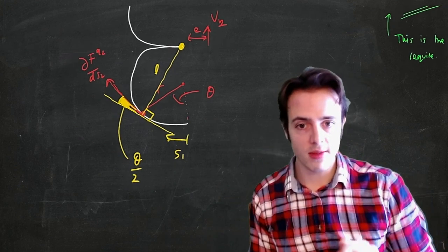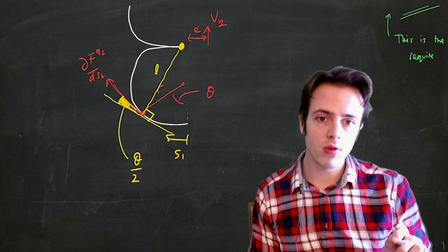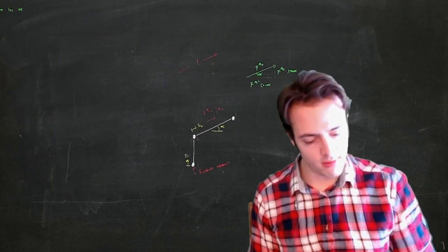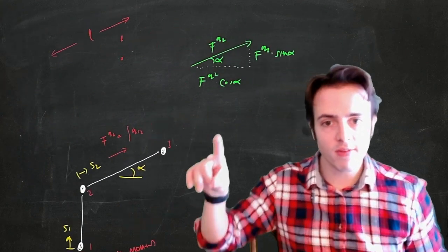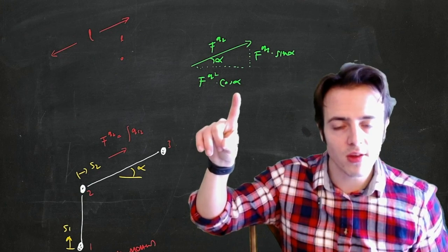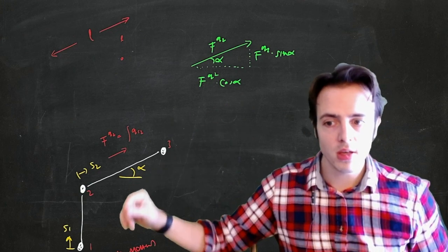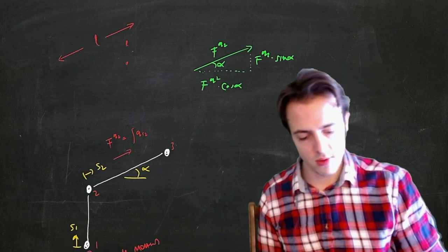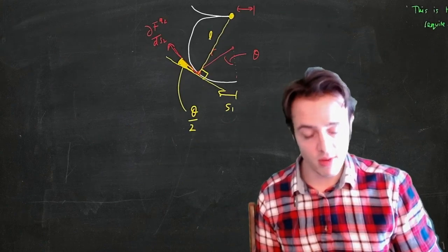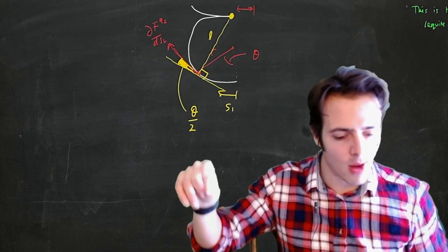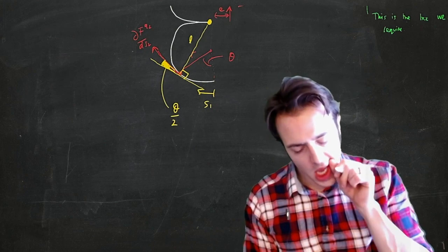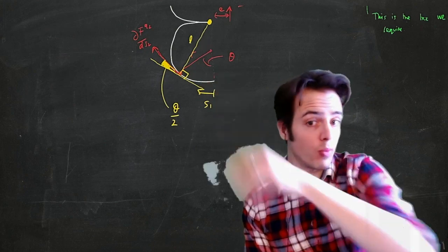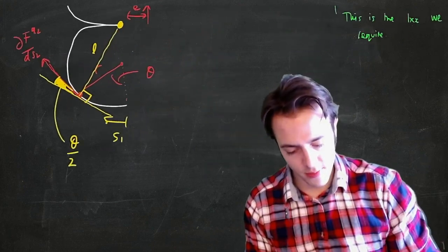So we know that the component of force, which, annoyingly, I've lost this diagram, but the equivalent of cosine alpha for us is now going to be cosine alpha on 2. Sorry, cosine theta on 2. So we've worked this out. This is effectively our alpha now. And then the moment arm here is going to be L, and we don't know what L is yet. We can work it out though.